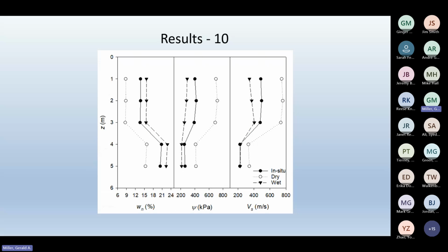And then it's the solid circles. And then he wetted those samples in a controlled humidity environment, which basically means he stuck them in a sealed container with a salt solution, having a known osmotic suction. They weren't touching the solution, they were sitting over the top, and that forced a change in suction and moisture content.